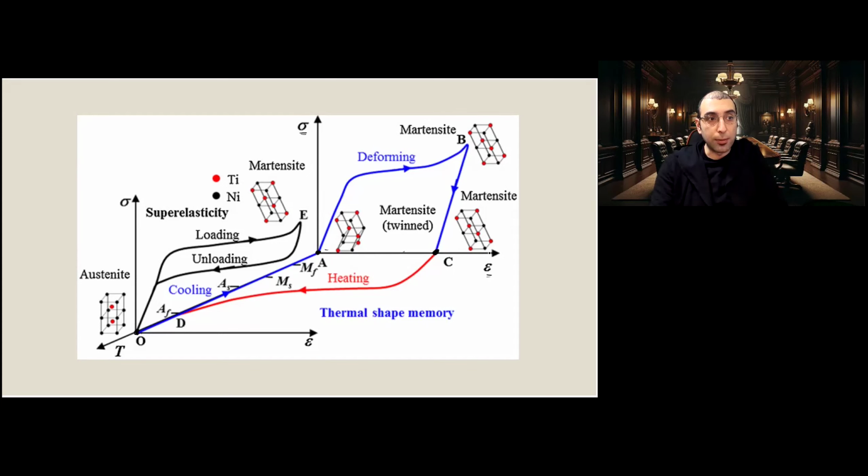So when we are discussing here, just like a normal alloy, you start with deformation and then you enter the elastic deformation region, which is the linear line here, until somewhere around this point, and this point is our yield point. After that we begin with plastic deformation, just like a normal alloy, and you get some strain hardening as you apply deformation, and this is our strain. When you project it down to the strain, you are applying deformation and you get strain hardening because your material is getting hardened. If you're unfamiliar with this concept, watch the previous videos.